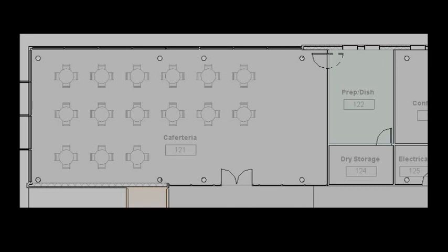So I thought about how I was going to explain this, and I know if I just showed you the script, I couldn't. So I made a flow diagram, if you will. First, we're going to make points in the room. This is to put our supply diffusers. Then after that, we're going to move those points, shift them over about half of the distance that we put them. This is ideal for placing diffusers.